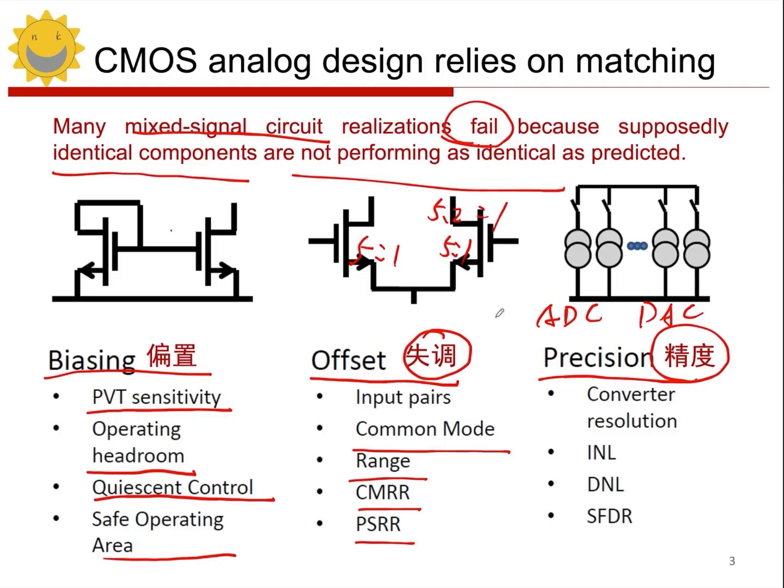For our two capacitors, C1 and C2, we want the value of C1 to be equal to C2, and we can achieve a closeness of about 1%, or 1 part in 10,000. This is definitely possible. In ADCs or DACs, we often use the ratios of passive components, like capacitors or resistors, to perform precise operations on analog signals. Of course, this needs to be combined with a negative feedback process.